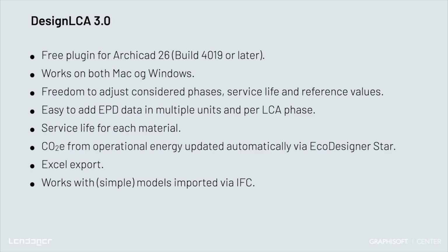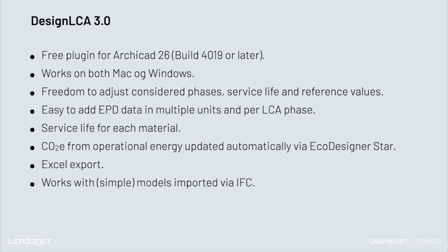It's easy to enter EPD data, no matter what unit. You can find the EPD data and what different phases you want to include. There's service life on all materials, and it will calculate the CO2 from operations using EcoDesigner Star. There's Excel export, and you can import IFC models from other programs.